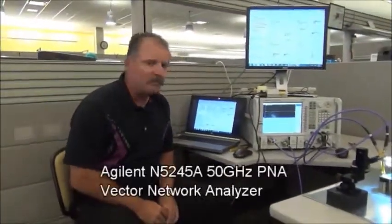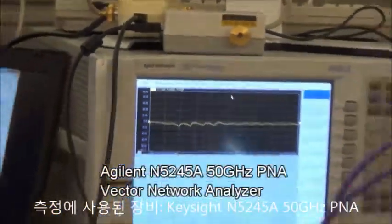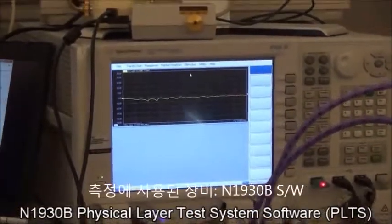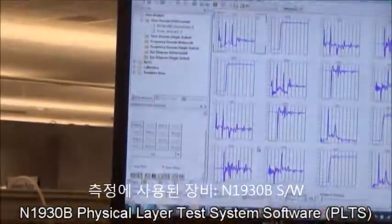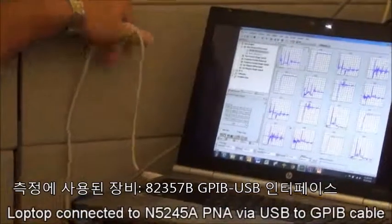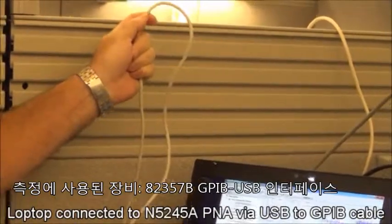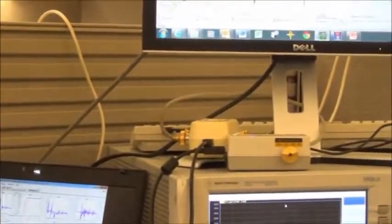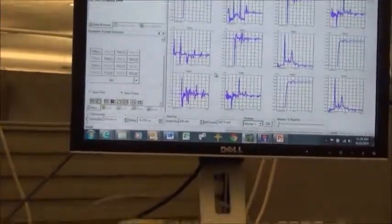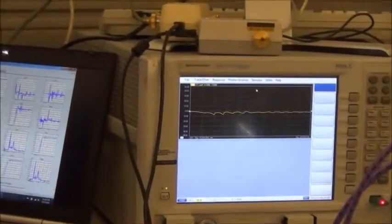Let me introduce the equipment we're going to be using for this experiment. Right now we're using an Agilent PNA, an N5245A vector network analyzer up to 50 gigahertz. We're running the physical layer test system software, PLTS, on a laptop, and we're connected from the laptop to the vector network analyzer with a USB to GPIB interface. Very easy connection for communications. We can control the calibration and the measurements of the VNA, and then afterwards do post-measurement analysis on the PLTS software.